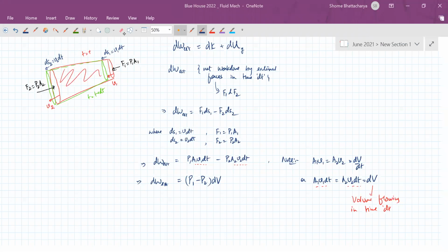Sir, we are writing this equation by taking into consideration that the fluid flowing through the pipe is an ideal fluid. What if it was a real fluid? What would the equations be? See, in a real fluid, first of all, the continuity equation will have to be modified. There would be friction on the walls, and viscous force also, the equivalent of drag force. In this, we are not considering the viscous force, because we are dealing with an ideal fluid. It's non-viscous in nature.